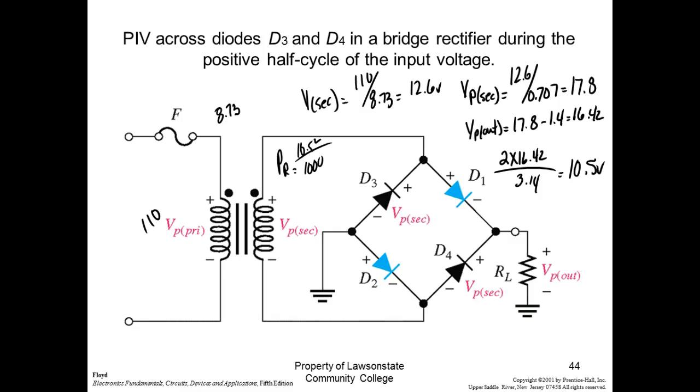So a 100 ohm resistor is not equal to a 100 ohm resistor. People think I can use any 100. We used to teach power supply design. And once the student built their power supply at home, that was their project. They brought it in, and then they had to do all the specifications on it to see how much current it would put out. They designed it for a certain amount of current, and then they'd see how much it would put out. And they kept saying, something's wrong with my power supply. It keeps burning up these resistors. And there wasn't anything wrong with the power supply. They were trying to use a 1/4 watt resistor on a 30 volt supply. Okay, you'll understand that. So the best way to do it is to know your power formulas.